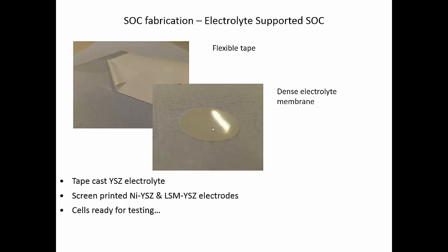Typically density is somewhere between 95 and 98% dense. You need to be above the open porosity density, which for ceramics is approximately 92%. So if you're above 92% density, you won't have open porosity, and therefore your cells should be gas tight.